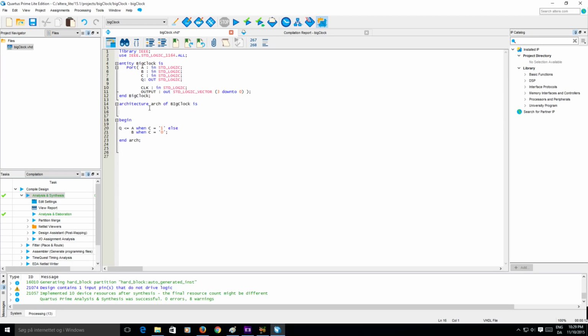And if we wanted to make a signal in here, we could also do that. We use the signal keyword, then we need a name. Could be something. And we make the colon. And we don't need to specify if it's an input or an output. It's just a general purpose signal that we can use for anything. But we do need to type the type of signal, and then a semicolon. And it's a good idea to give these a value, and you can do that by typing colon equals, and then, for example, 0.